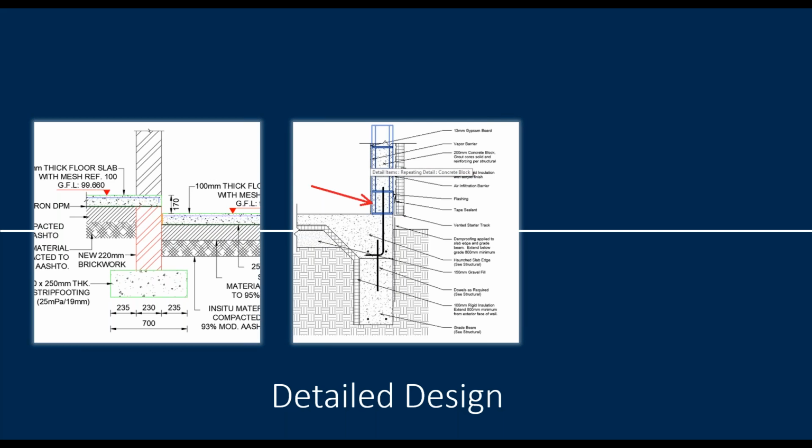In a 3D environment, it will look quite similar because it's something that's going to be printed on a 2D drawing. But what's different here is that the lines actually represent elements. So what you're seeing highlighted is not only lines, but it gives you information about what that is. So I can see that's a detail item that represents a concrete block. And what's really nice in Revit, because this is sort of an intermediate way, is that this is not necessarily modeled in 3D, but still the detail item that you're seeing has got some intelligence built into it that identifies it as a particular element of a particular size with material properties and things like that.